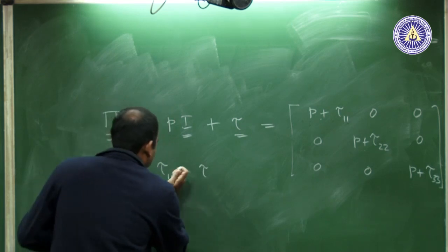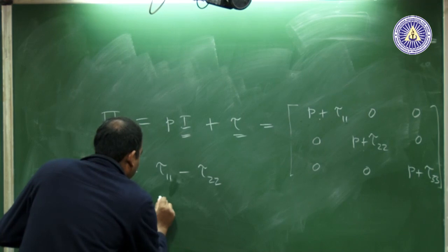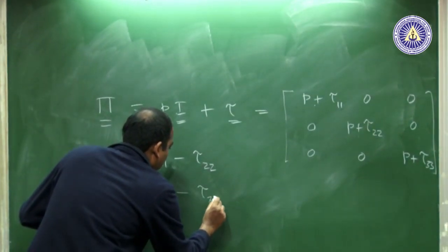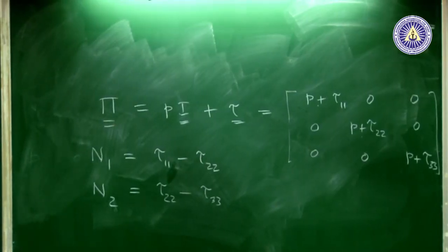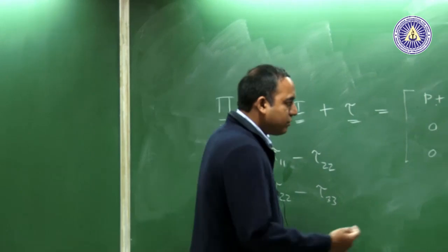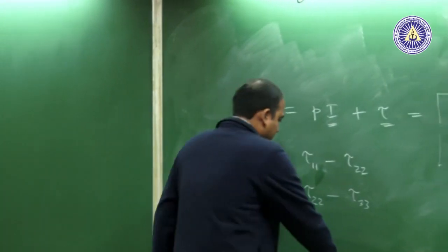So, you do not have the contribution from the pressure, and you can rely solely on the differences of deviatoric stresses. That is something we have to keep in mind while doing experiments with non-Newtonian fluids which are also incompressible, which is true in almost all chemical engineering applications.